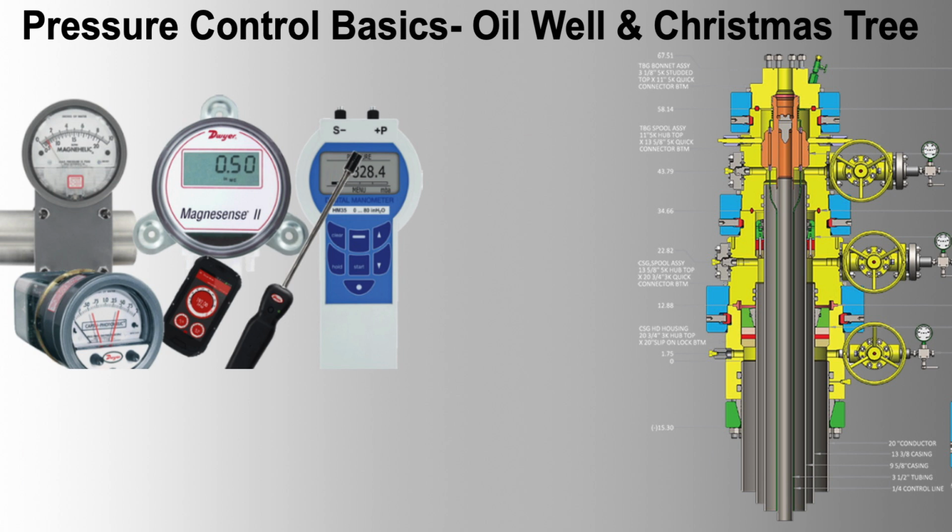1. Example 1. Wellhead pressure transmitter for sour service. Instrument type, differential pressure transmitter. Accuracy, 0.1% of full scale, Inconel 625 for wetted parts to resist sulfide stress cracking. Installation, directly mounted on the wellhead with a remote seal to isolate the sensor from high temperatures. Other criteria, HART communication protocol, ATEX certification for explosive environments.